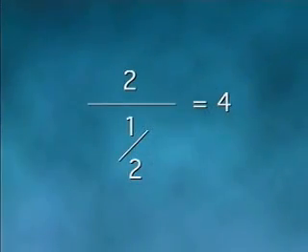In our example, the size of the packing is 1/2 inch. The depth of the stuffing box to be filled with packing is 2 inches. Dividing 2 inches by 1/2 inch equals 4. So 4 rings of packing are needed.